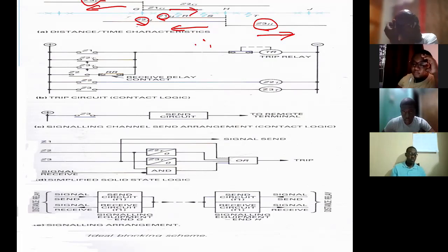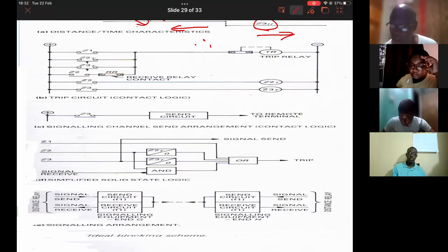All right? So the big difference in terms of the settings is that the zone 3 settings are looking in the opposite direction. So let's now look at the logic circuit, the solid state and the contact logic, to see how this system works.